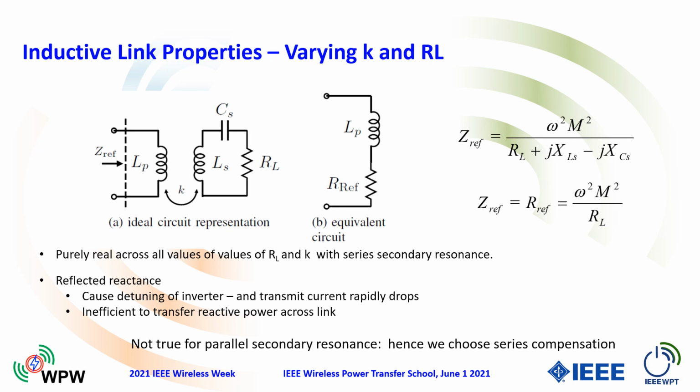With parallel tuning, this is not the case. With parallel tuning, if you change RL, you will also then start to reflect some residual reactance back to the primary, and you will detune the primary circuit, and you will lose soft switching capability on that circuit.